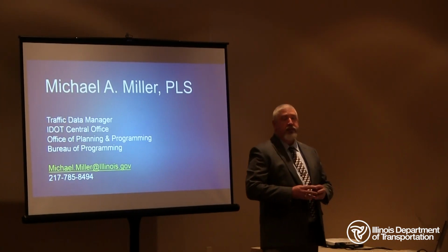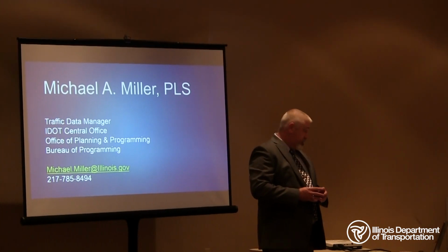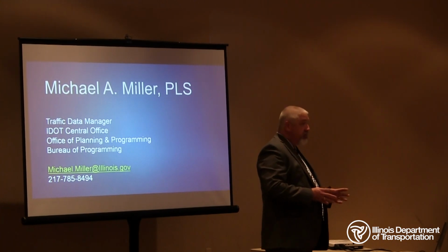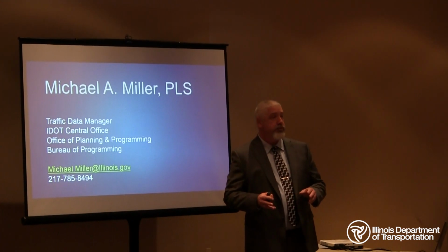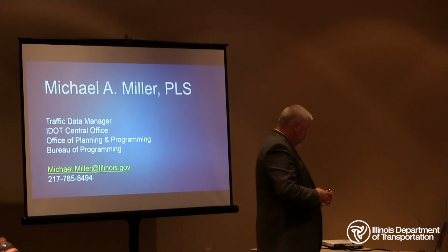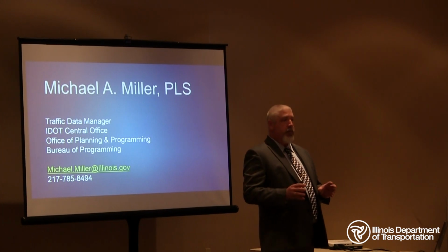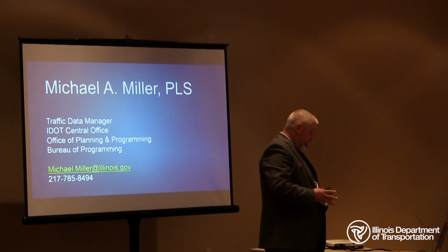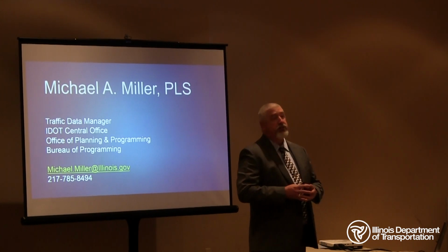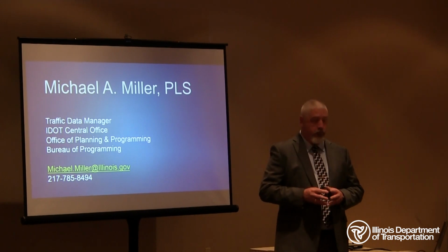Each of these points also contains associated metadata, such as RGB values and intensity return values. These values allow you to delineate features within the point cloud. So basically, a point cloud is a working 3D model that can be used for numerous things, including asset inventory, design, as-built, etc.